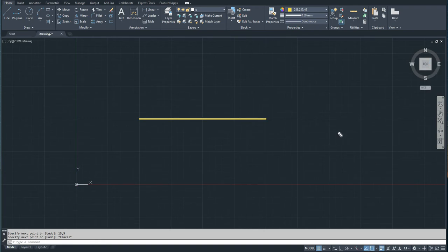Now this is called the absolute coordinate system. That means every time I want to enter a point, we have to measure the x and y from the 0, 0 point, from the reference point. Now guys, suppose that I will go to this point, and this distance from here to here is also 5. So how can I go there? We have to go in x direction from here to here, which is 15, and go from here to here, which is 5, and again 5. That means it is 10.